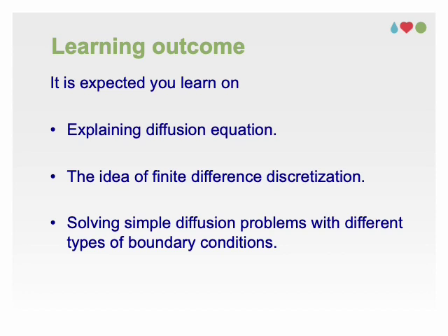This is because the diffusion terms in the Navier-Stokes equations refer to the transport of momentum or energy due to molecular or turbulent diffusion. The finite difference method is particularly useful for solving the diffusion equation because it is easy to implement and computationally efficient. It can handle complex geometries and boundary conditions, and it can be applied to both linear and nonlinear diffusion problems.